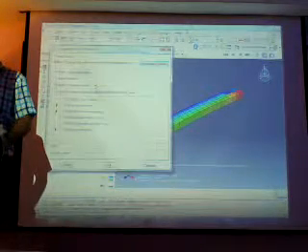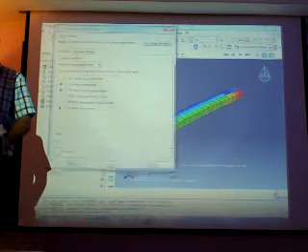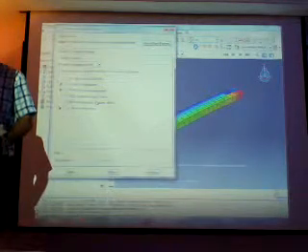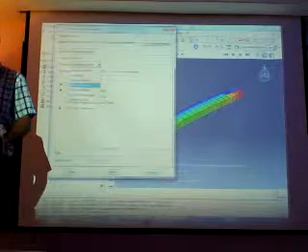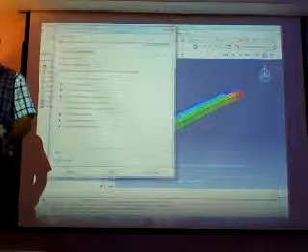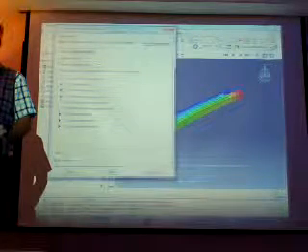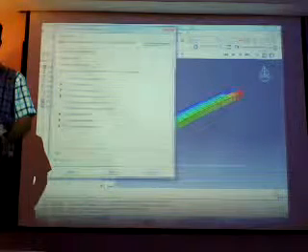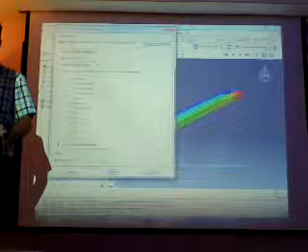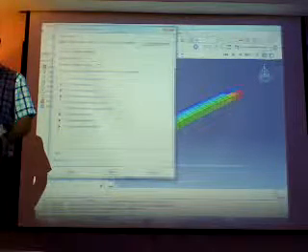You can see here we have a different kind of output. This simulation by default calculates different things for you. For unique node, for example, we have different kind of outputs: equivalent plastic strain, or reaction force, or stress component, for example, Mises or maximum principal or another.